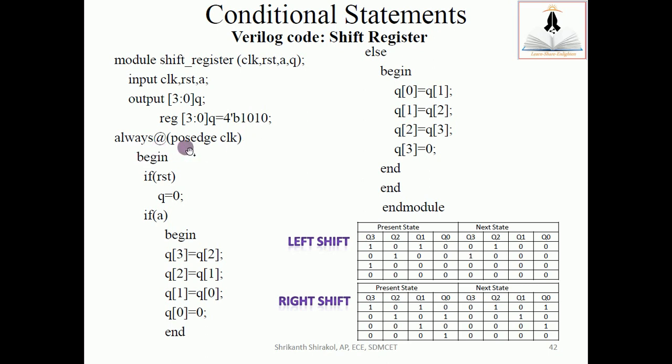So always at the posedge of clock, if reset is 1, Q should be 0. If reset is 0, then this particular statement will be executed.